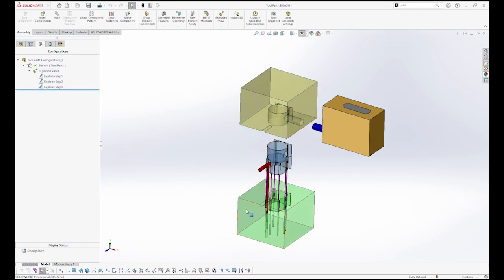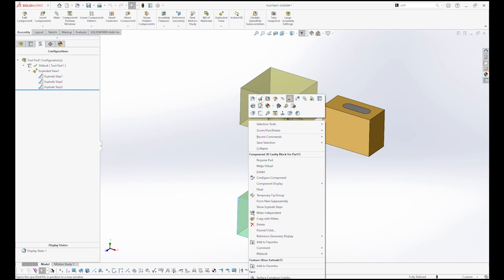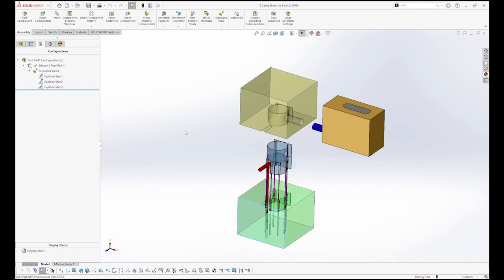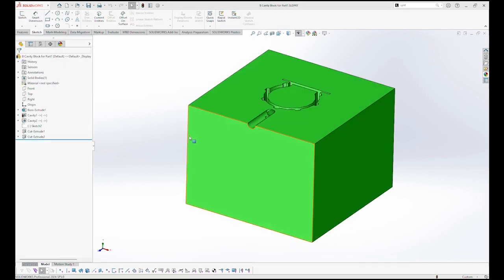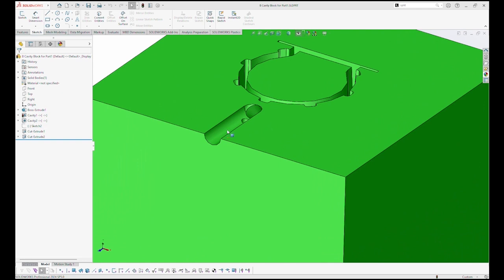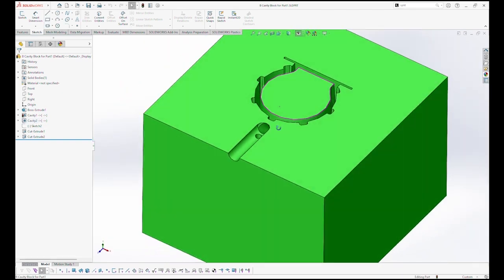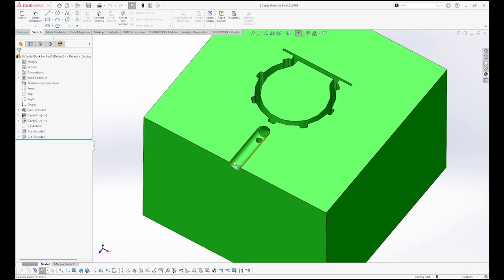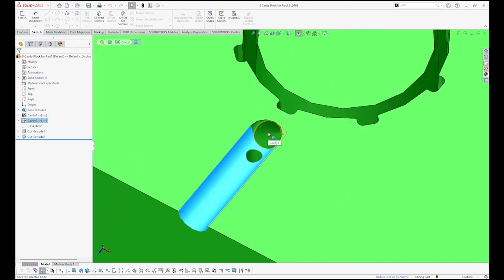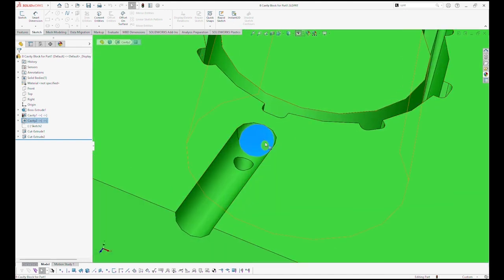What I want to do is go take a quick look at the B side cavity block. So here's that B side cavity block. This is where the runner, which was the red component in the tool assembly before, this is where the molten resin comes through. This area here is called the runner, and then this funnel here leads to the gate opening.